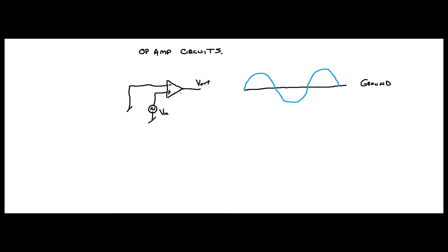Think about it. When your non-inverting input is at a higher voltage than your inverting input, your result is going to be high, isn't it? So at this point, it's above, it's going to saturate. This point right here, I'm going to just call it VSAT for V-saturation, right? We've already talked about that. Now, at this point, it crosses zero again, doesn't it?